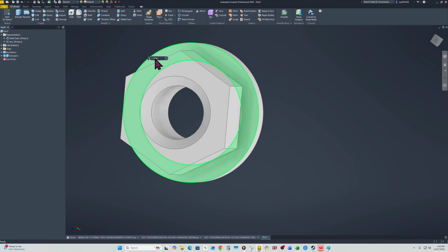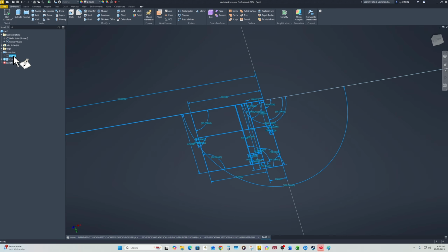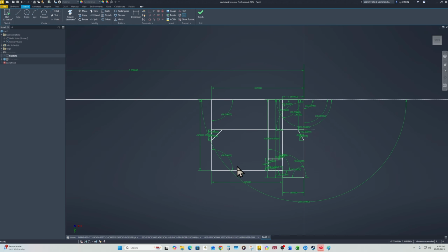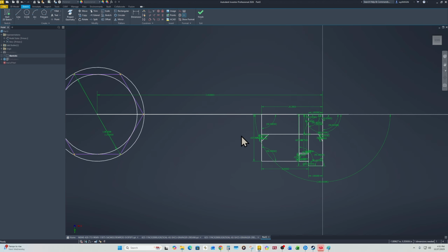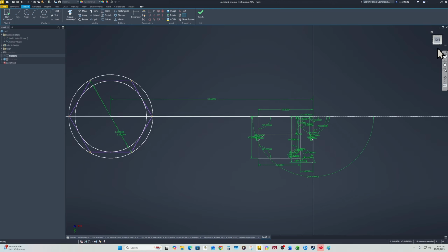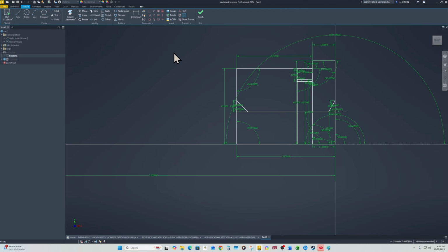And I forgot, we could have just done it over here because the diameter is 1.25 for the hex. Right, so that's the smallest diameter it needs technically, right? So I'm gonna double click on the first revolution sketch. Is that why I had this? That's why I had done all this. Yeah, I didn't even use it.